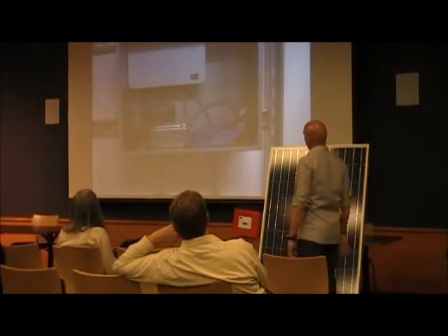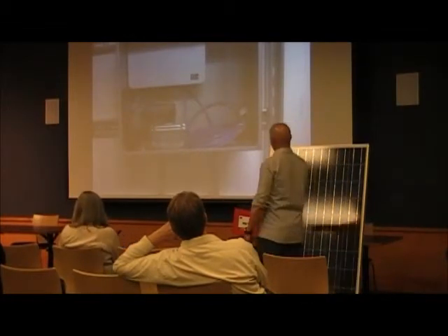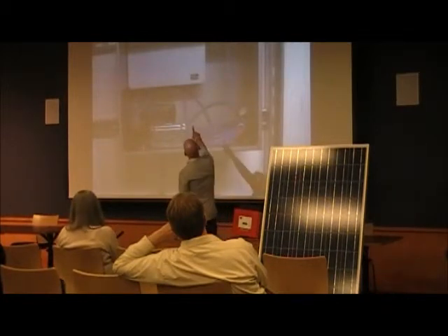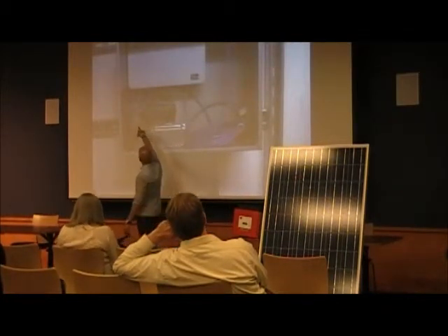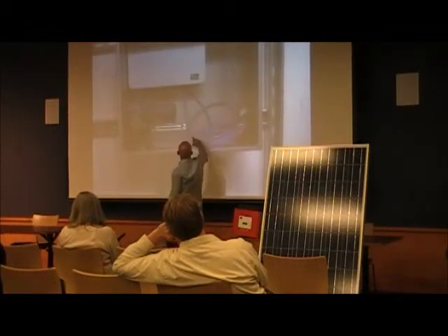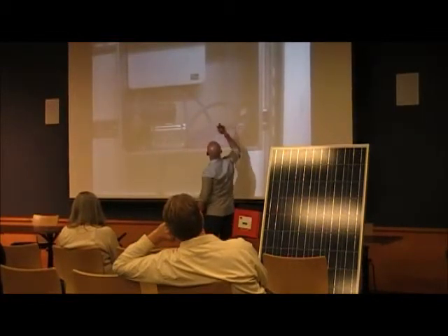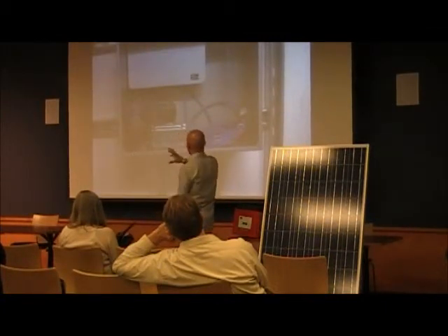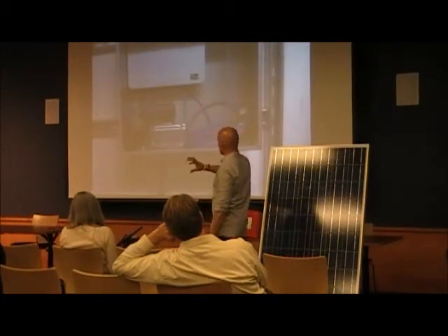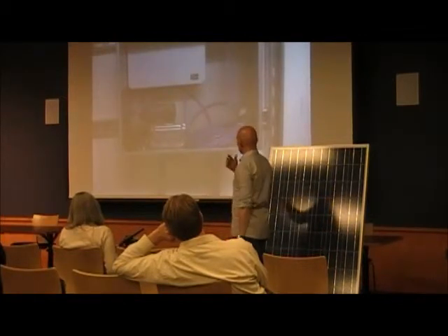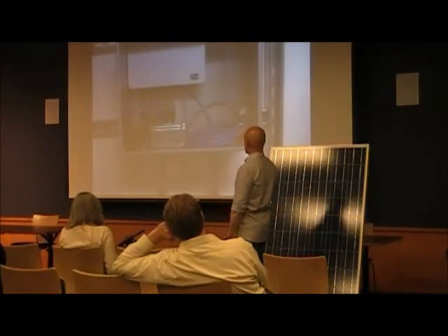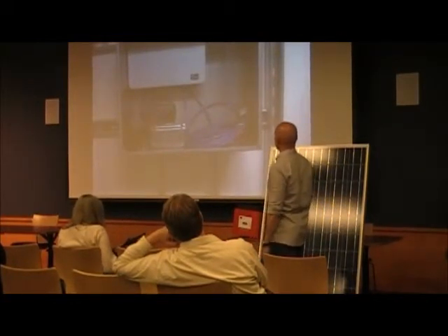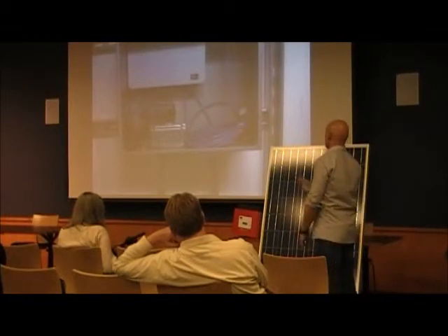So that's what that looks like, just hooked up. You have an inverter cable, and there'll be a Cat 5 cable that pops out of this guy and runs all the way up into the SMA box right here. This will filter data, and then it jumps into another Cat 5 and runs all the way up into your router, and then that pops into a server program that the manufacturer has. Then you can jump on there, interconnect it, and start building your graphs out. You can demonstrate all kinds of different ways to show how much power you're making. I was trying to get a picture of what that looks like.